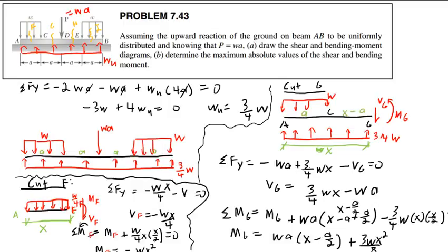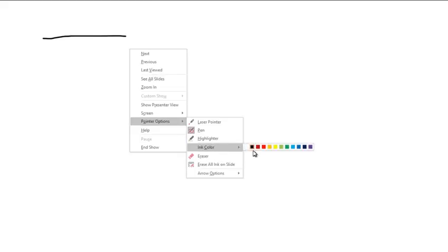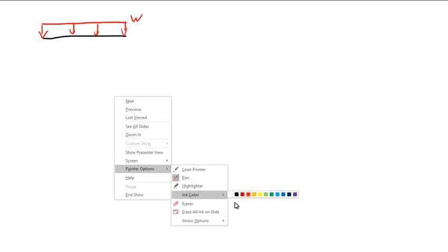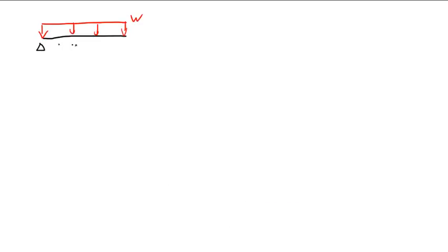We could take advantage of symmetry, but you'd need to know a bit more. Yeah, that would actually work. You could plot it and then mirror. You could simply mirror the plot. But yes. Well, actually, you got to be very careful with that because it's not simply a mirror. For example, what I mean by that is you cannot simply mirror it because, for example, the classic example is a symmetric, simply supported beam with a load W on it. If you have a load like that, what does this look like? Well, let's see. Say this is length L.